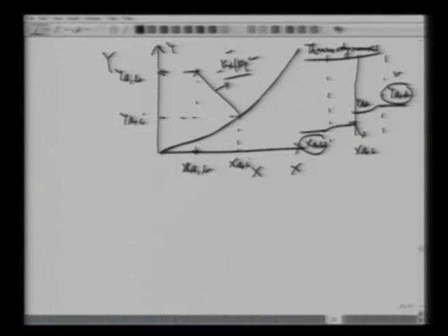What we know is possibly the bulk concentration, because we can measure that sulfur dioxide is 1% and how much is the water concentration of sulfur dioxide. So we know this point here. Now if we know the operating conditions, say Reynolds number and Schmidt number in the gas and liquid phase, we can calculate Kx and we can calculate Ky.